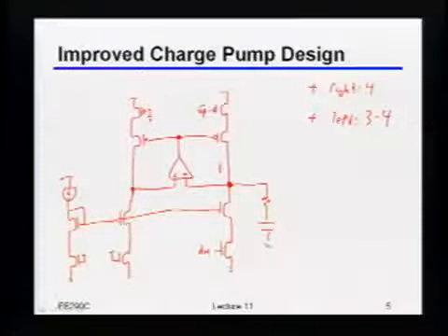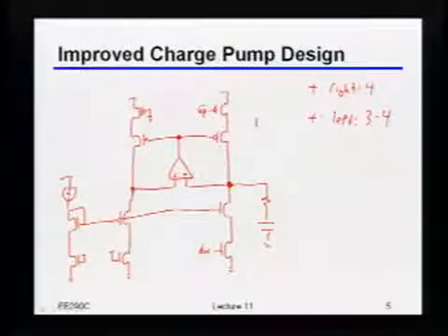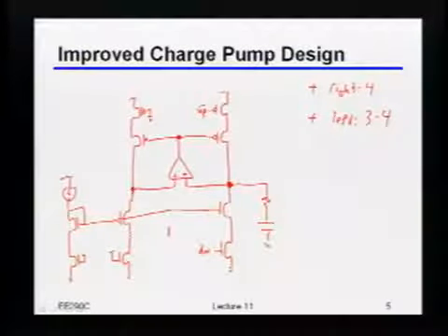So this is actually now starting to be a fairly common charge pump design. Because of some of the charge injection issues we talked about, you might even add some injection cancellation switches and things like that. But basically, this is fairly realistic. Building this little op amp here is also a little bit fun because you have to be careful about the stability, and because the range of voltage you want to tolerate here is pretty wide, you might need a wide input range on the op amp. But basically, this is really starting to look the way real PLLs are built. Make sense to everybody?